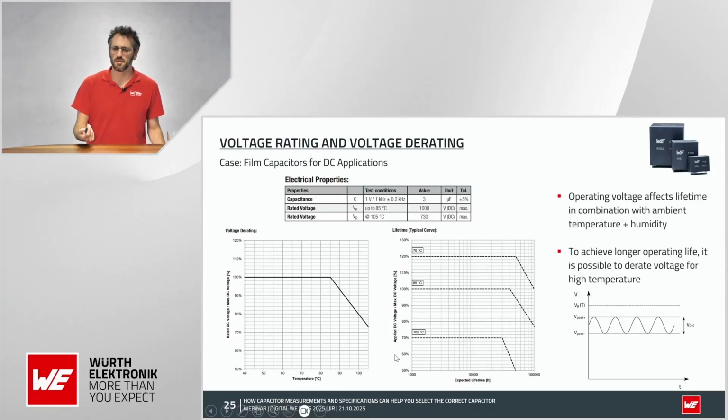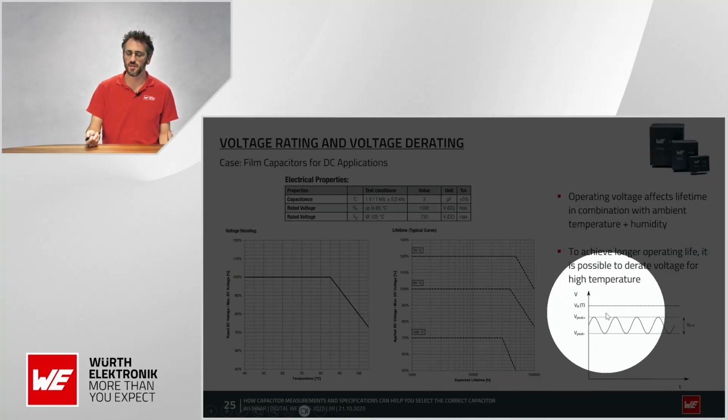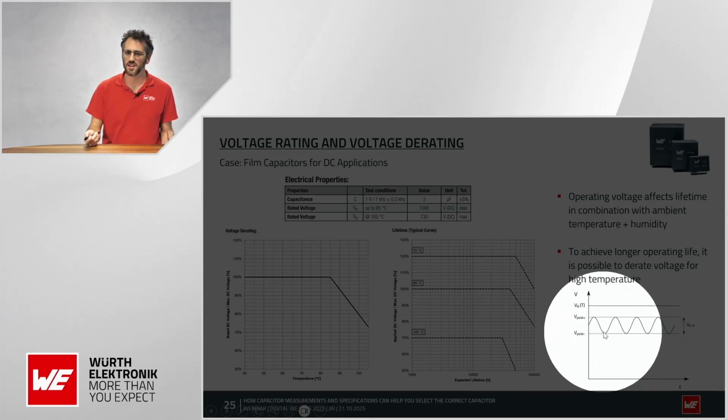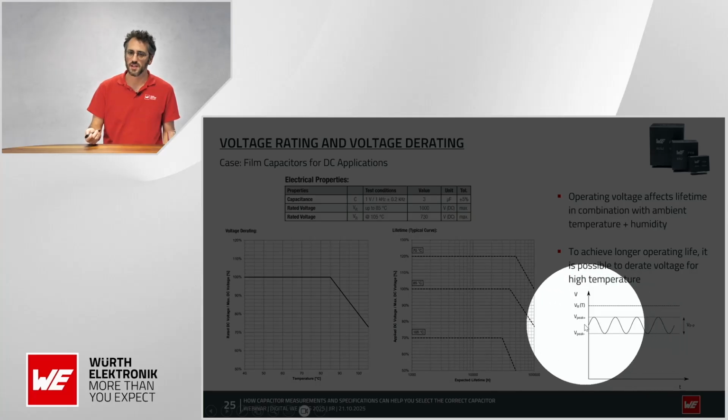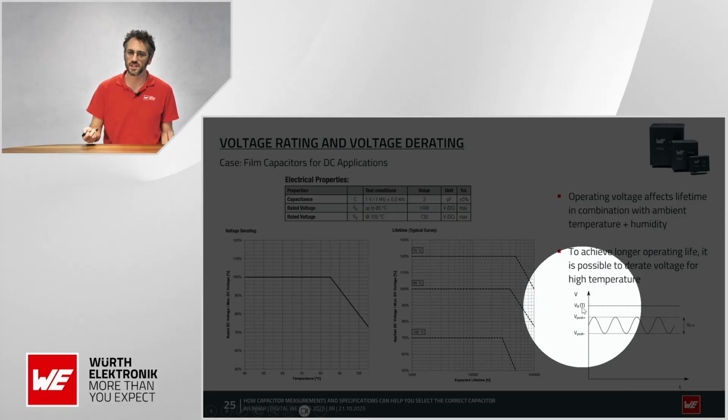Another thing about rated voltage, when we say rated voltage, we include the ripple or the peak of the ripple that you include. In this case, you can have a high ripple in your application, but you should never surpass the rated voltage rating that we mentioned before.